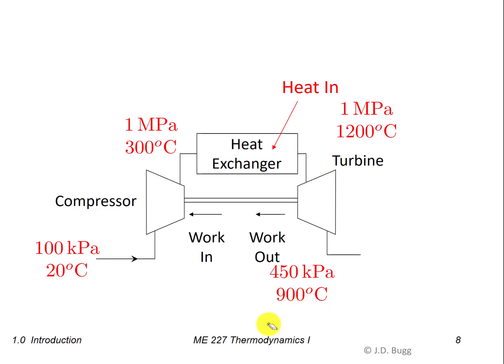So this is where this cycle gets a little bit different than the last one. The last component in this cycle is a nozzle, and we didn't see a nozzle in the Rankine cycle. So a nozzle is something that takes hot pressurized gases and increases the velocity. So there's lots of energy stored in here, but it's internal energy because it's there as a result of being at a high temperature. But the kinetic energy of this fluid is actually quite low.